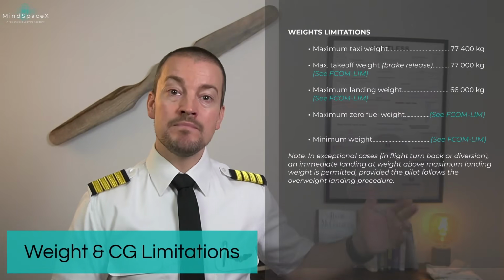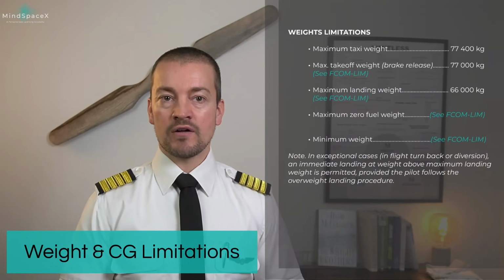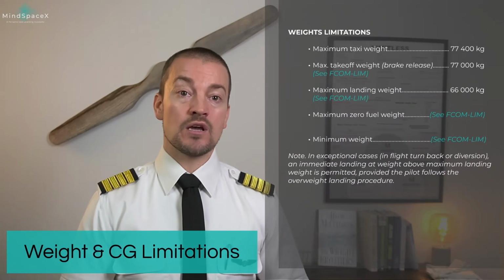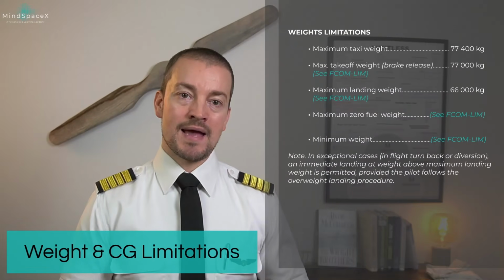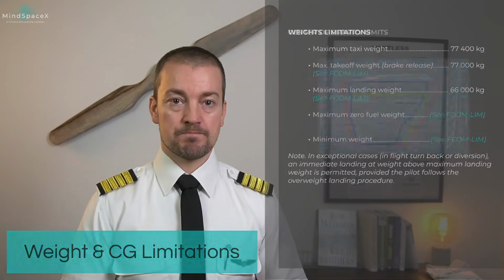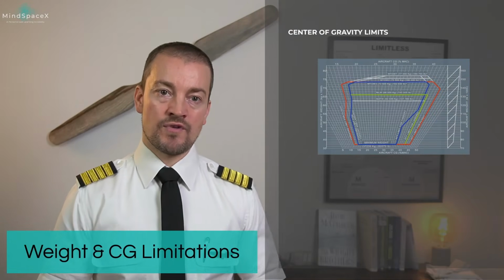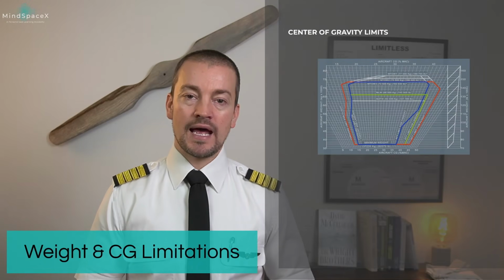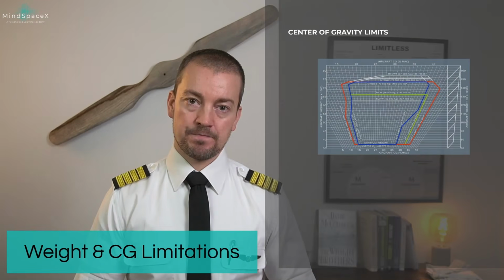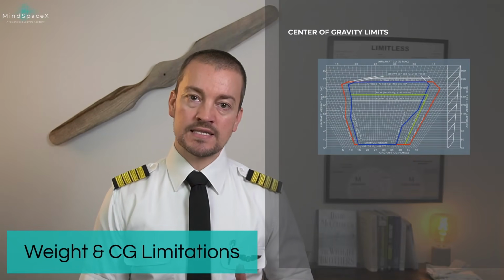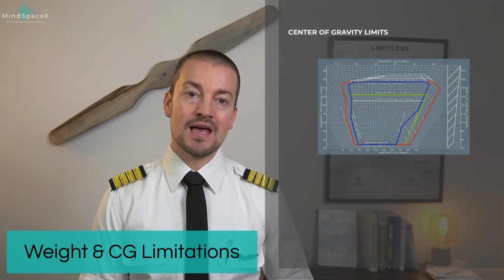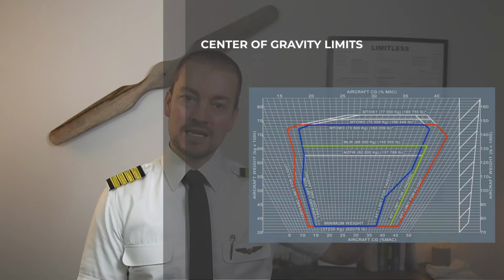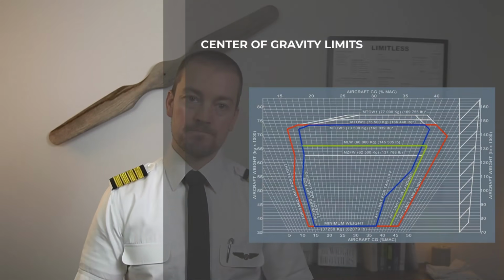Maximum fuel weight and minimum weight on the aircraft can be found in the A320 Limitations chapter, and the dry operating mass can be found in the weighing schedule and in your mass and balance documentation for the aircraft. The limitations on center of gravity are placed to ensure both maneuverability and controllability of the aircraft. As we covered in great detail in mass and balance in your ATPL theory, and again during the performance course here in the 320, the CG limits right here must never be exceeded.